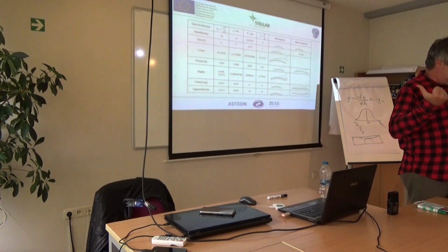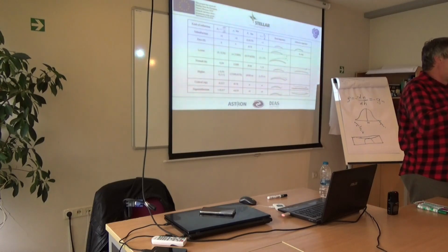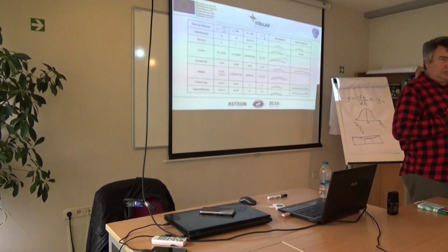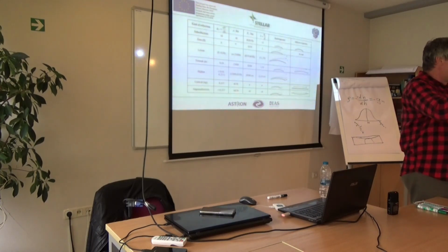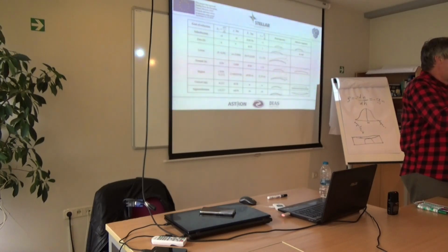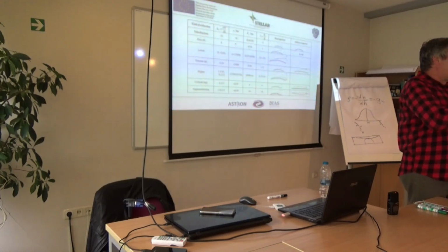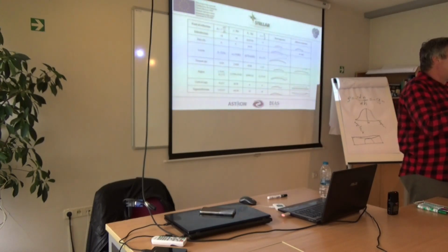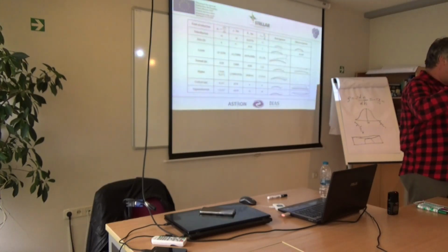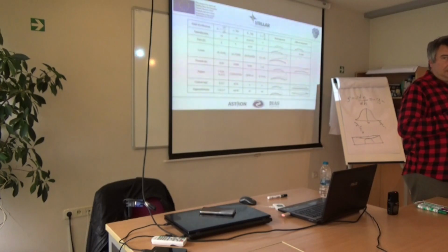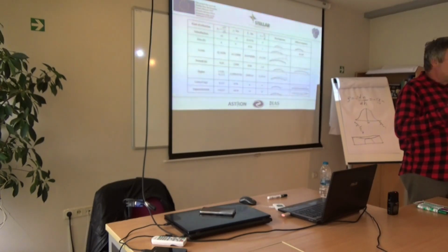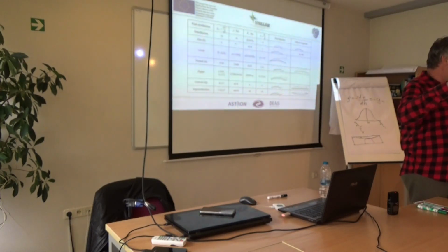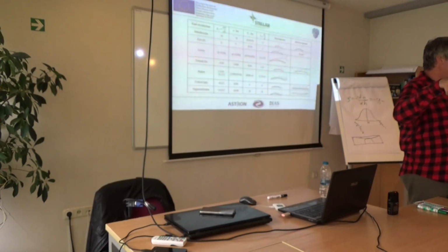Now I will speak about rain attenuation. We have different rain rates, and you know that heavy rains occur in a very small time for a given period. If we have a 1 year period, for example, very heavy rain we will have, for example, for 1 minute this year, and we use some rain rate level to calculate the link budget of the radio link.